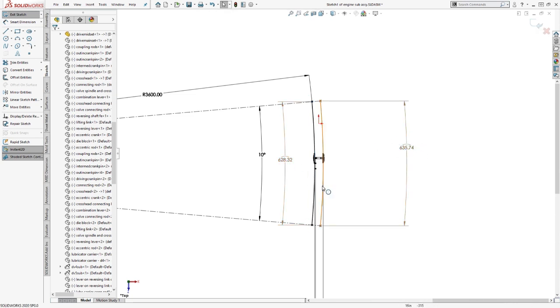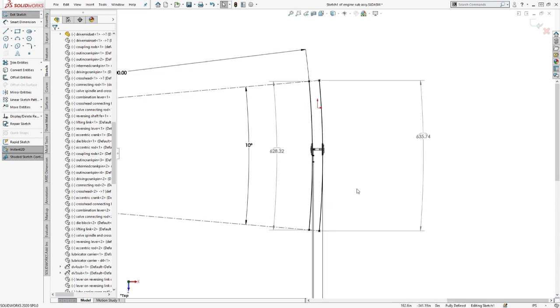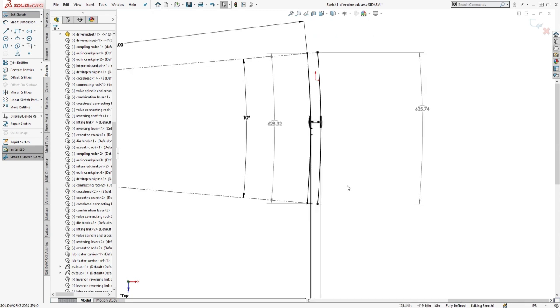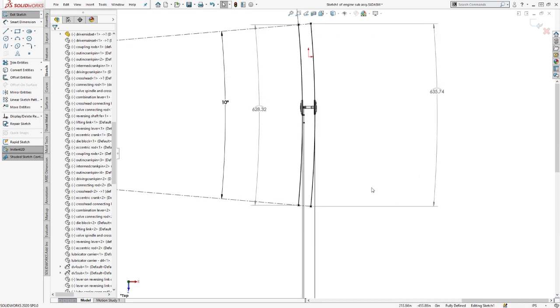Now, if we had a straight axle with two tires of the same diameter and therefore the same circumference, the distance that tire travels is going to be the circumference times the number of rotations. Well, in this case, we know how far we want to go, so we divide by the circumference, and that's how many rotations we need. With a fixed axle, same size tires, we're going to have that same distance over here.